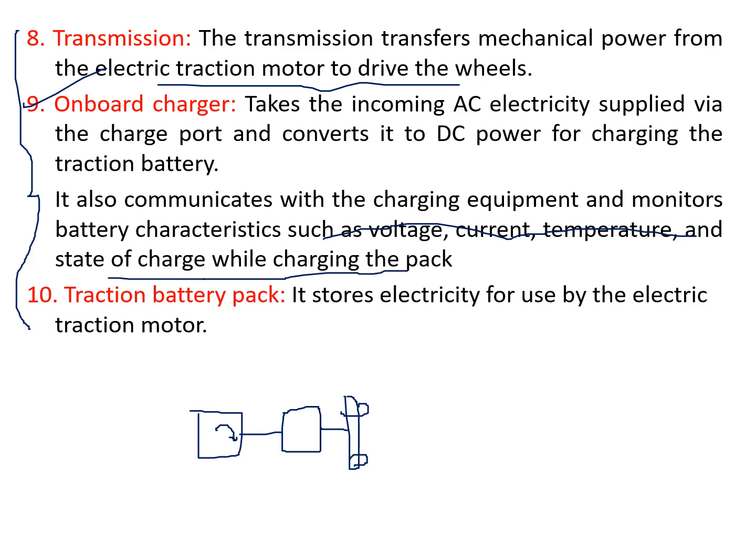Once we put the battery on charging, who has to check the characteristics of the battery? Because we have some time frame, right? Voltage level, current level, temperature level, and state of charge, state of discharge, we should know all of these for the charging purpose.